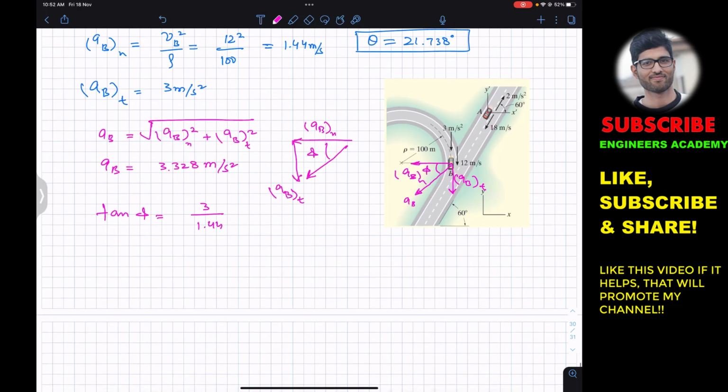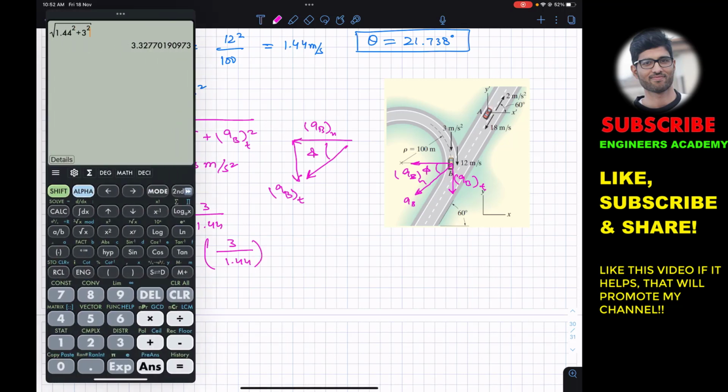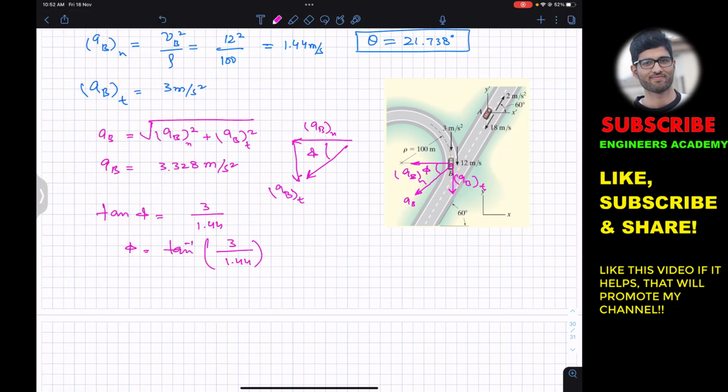From this we can say that phi is tan inverse of 3 divided by 1.44, which gives us 64.359 degrees. So now we know that the acceleration of B is acting in this direction, and it is making 64.359 degrees with the horizontal. This is that angle phi.